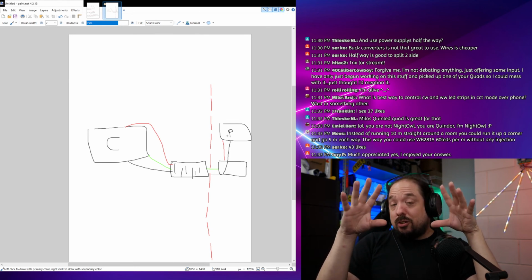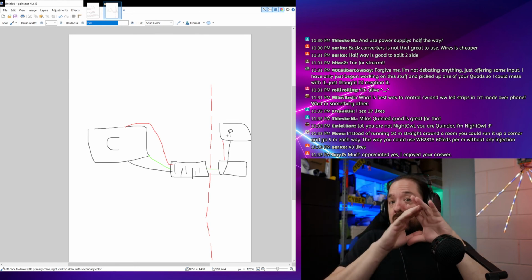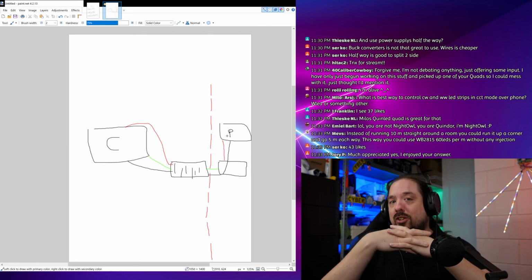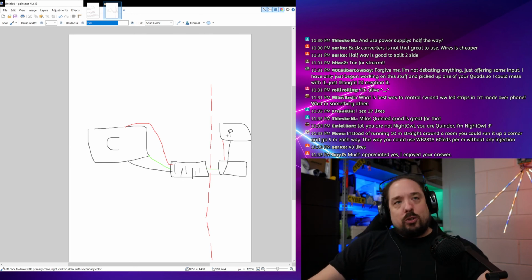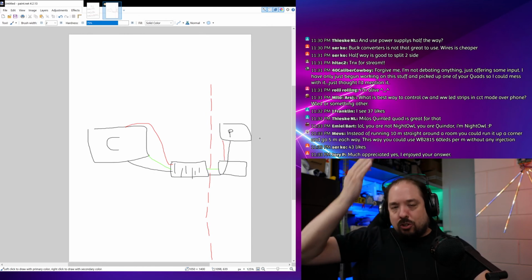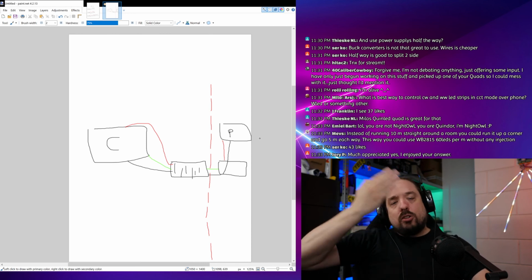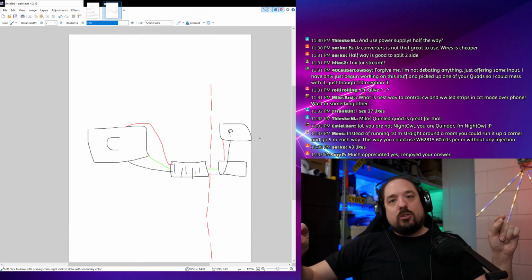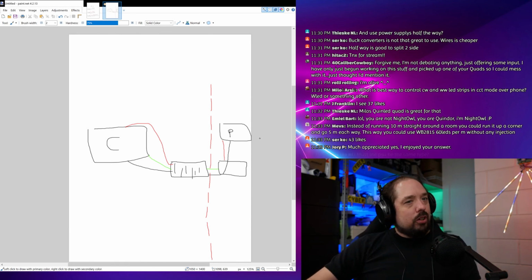That is going to be a really, really nasty scenario. Do not use multiple power supplies unless you know what you're doing. One of the ways to do it is by using split positive voltage planes, so you can keep continuing this. If you have a third or fourth or fifth power supply, that's fine, but you need to chop off those positive planes, connect all the grounds together, and then it can work.